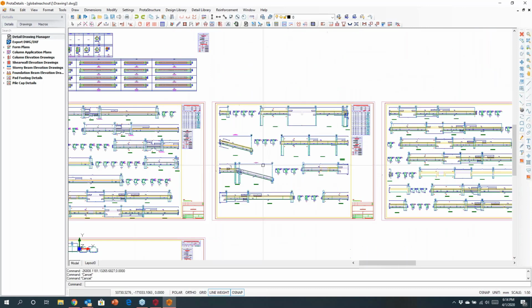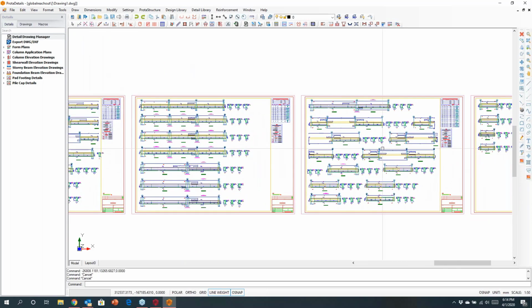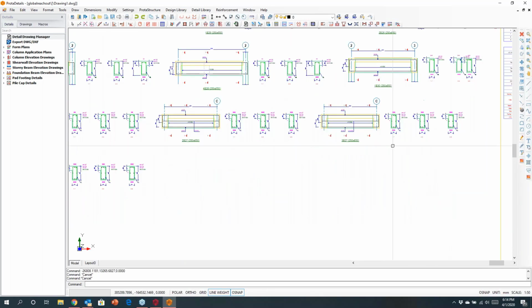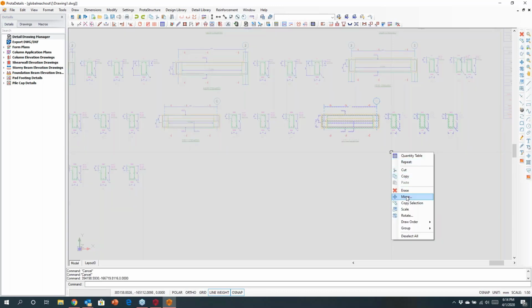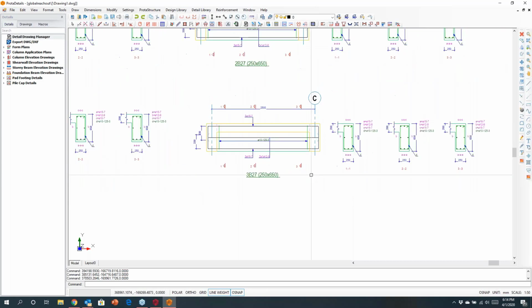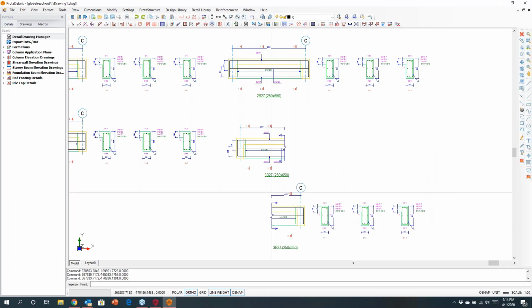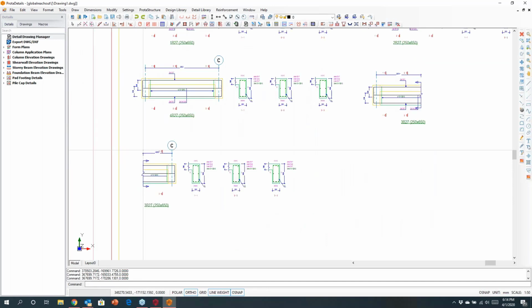You might recall that I created a ramp earlier, okay, and you can just see the way in which we're creating details here. Now, you are in CAD, and you can pick up details and move them around. If you didn't want to place a detail there, maybe you want to move it down to here, or maybe there's other things you want to do. Perhaps you want to cut a detail and chop it and move it down. So there's some handy tools in here to help you with the drafting.